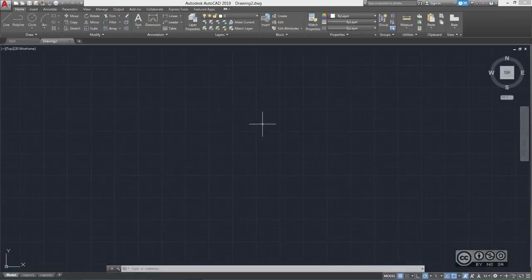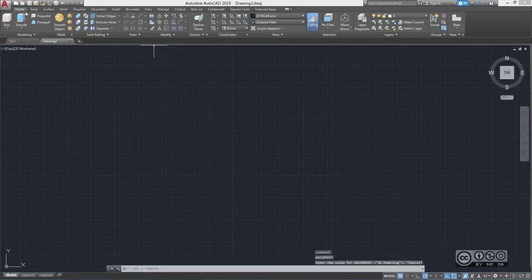So AutoCAD helps to design also in 3D, and the easiest way to make those changes in your toolset is by selecting this wheel and selecting, for example, in between drafting and annotations that usually is for 2D design, and by selecting 3D modeling I can see the 3D toolset. So that was about installing AutoCAD 2019 into your machine and firing it up for the first time.